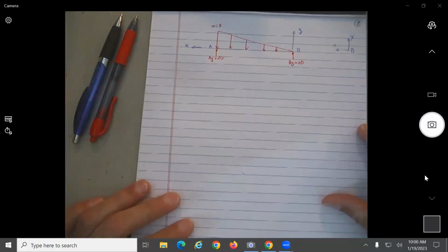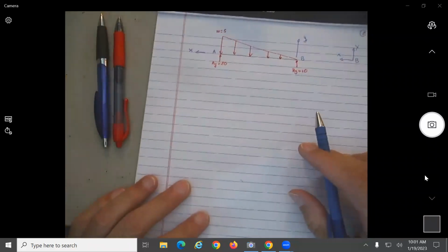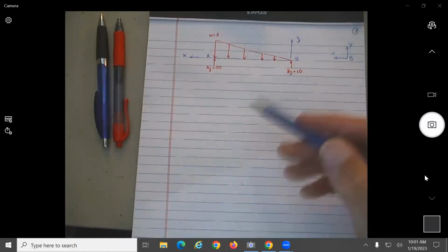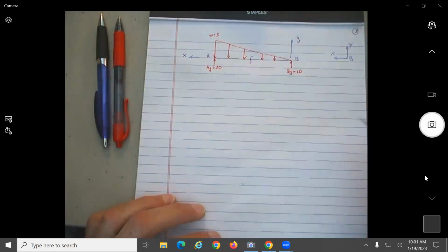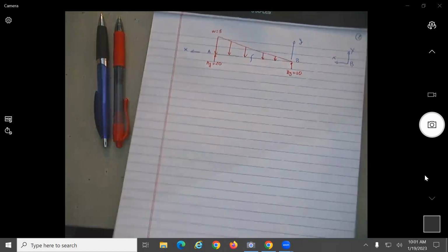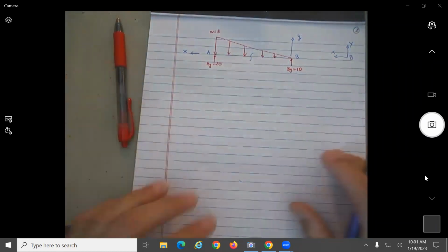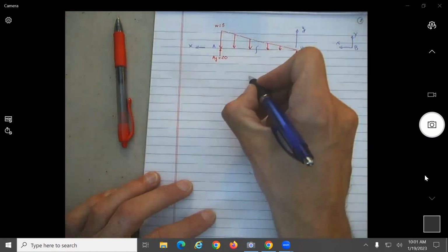So now, what is the procedure to find the shear and bending moment diagram? We need to make a cut so that the internal actions become external. How many cuts do we need here? Just one. So let's make that cut and we start from that end. Again, you see it's all the time the same procedure. What do we do now that we made the cut? We make a free-body diagram, no?